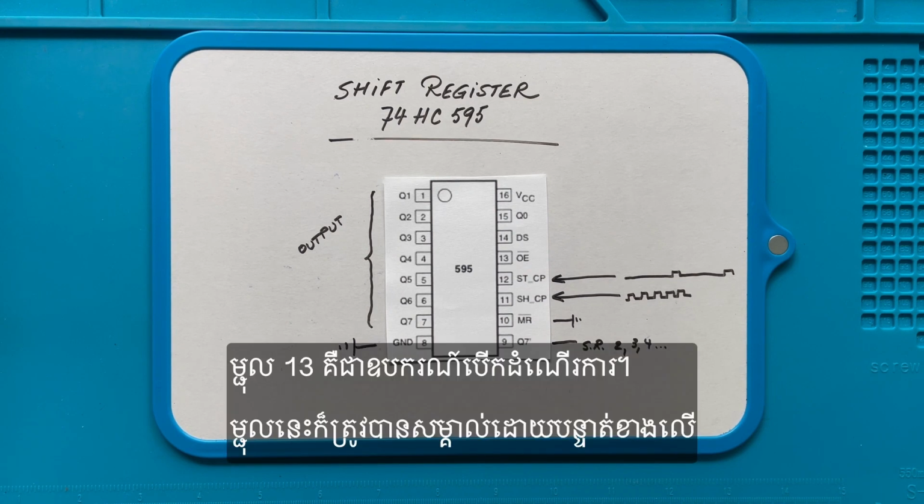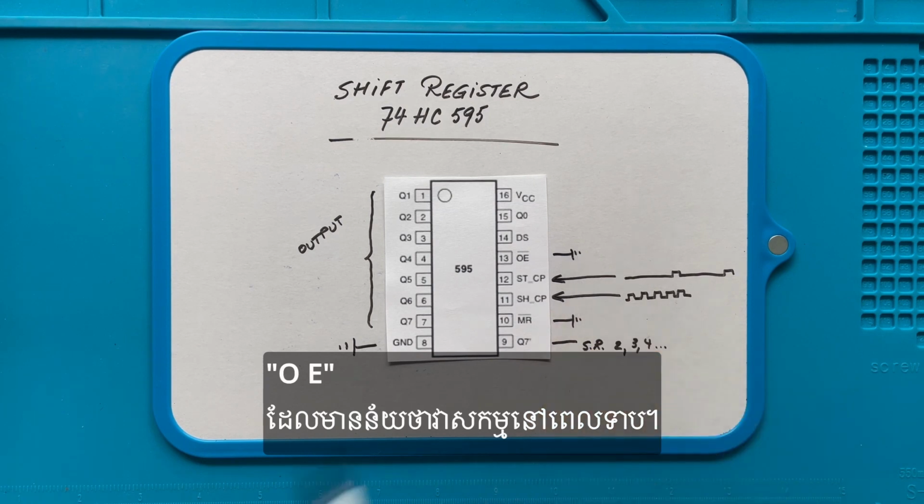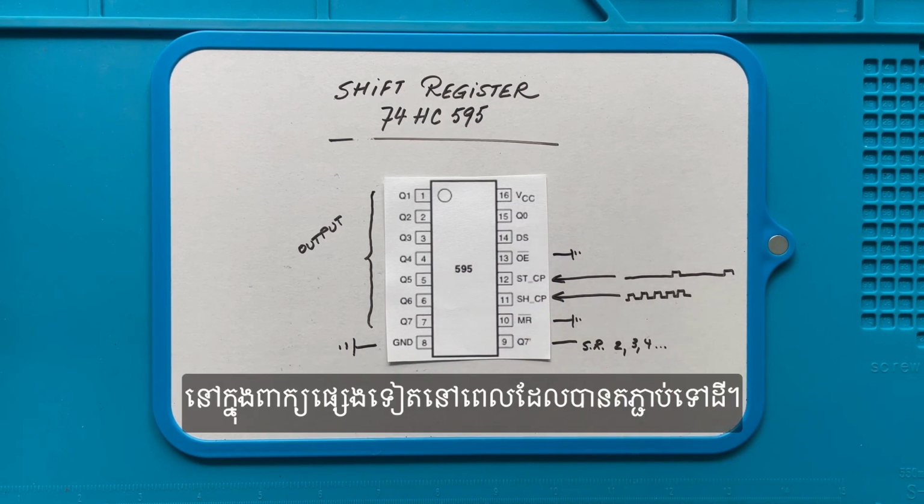Pin 13 is the output enable. This pin is also identified with a line above OE, which means that it is active when low, in other words, when connected to the ground.